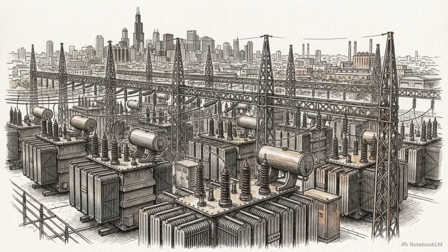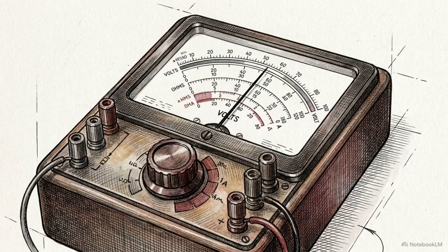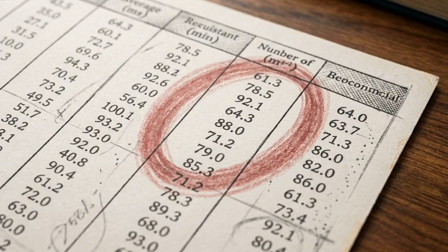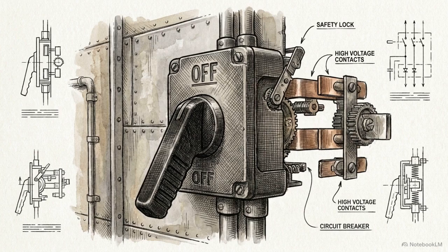Preventing catastrophic grid failure requires a method to measure this hidden physical displacement while the transformer remains online and fully operational. Historically, engineers measured short-circuit impedance. Variances over 3% signaled serious problems, but this required shutting transformers down.